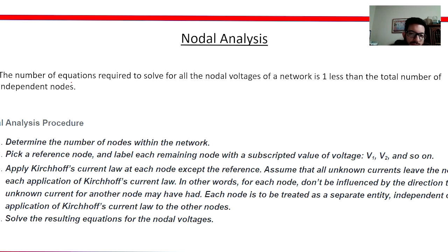So that was the mesh analysis. The other method, which it's really up to you which one you use. You can use either method anyway. But the nodal analysis has a few key steps. And it's similar to the mesh analysis in this sense. The number of equations required to solve all the voltages is one less than the number of independent nodes.